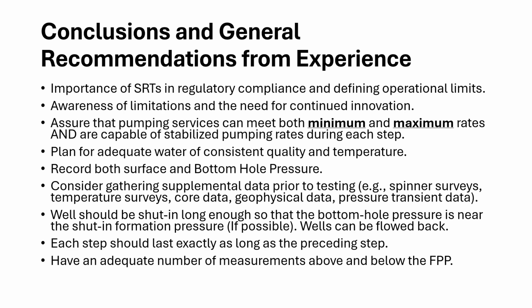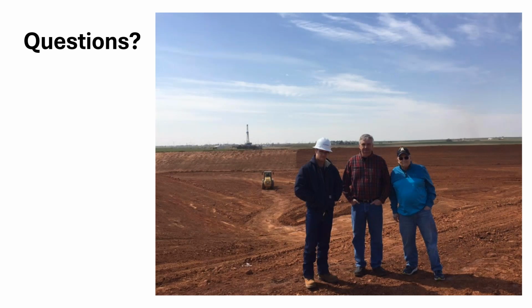If you do not have typically at least 3 measurements below and above the parting pressure, the test will be considered invalid. And that's it. I don't have much else to say unless you have any questions.